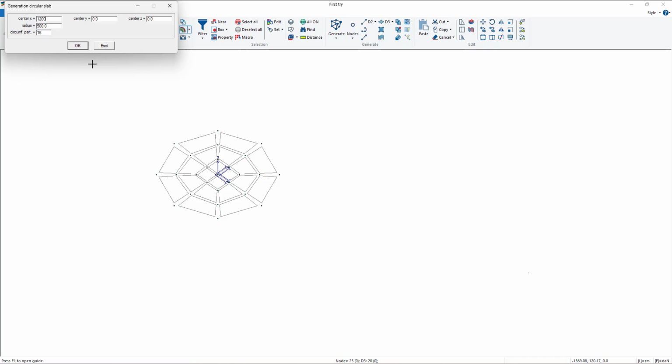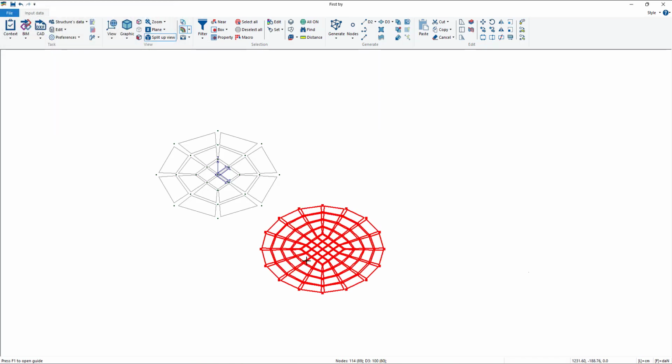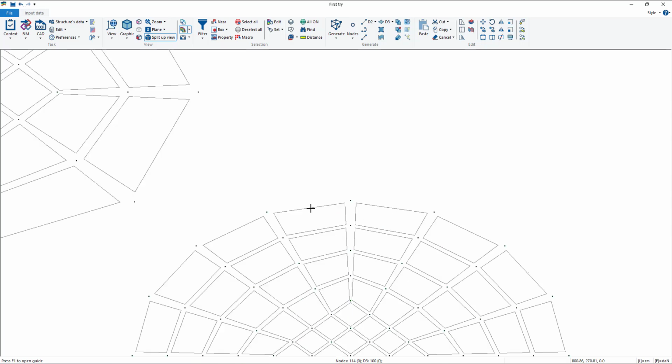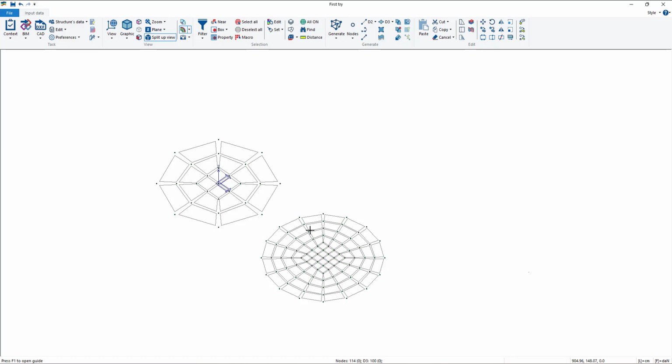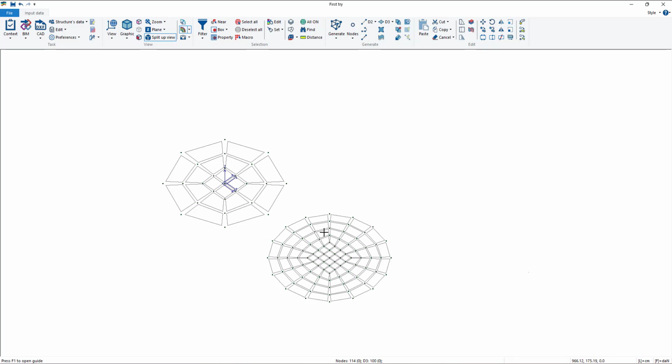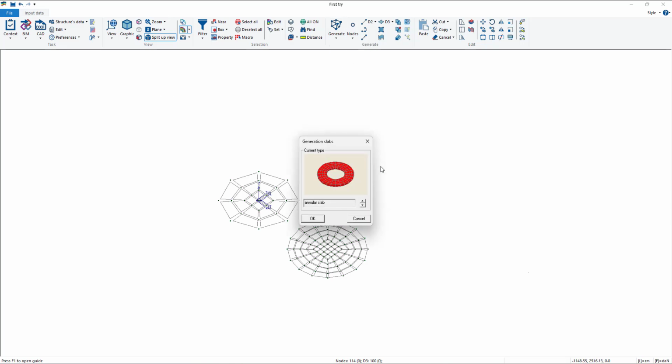If we go OK, we can see that now the radial division is 16 instead of 8, and of course also the linear division along the radius is higher, so we have 4, 5, 6 instead of 1, 2, 3, because the dimension of this side of the D3 element is exactly half of this, and so the shorter side of the 3 element is shorter. Okay. Of course we can go on with this.